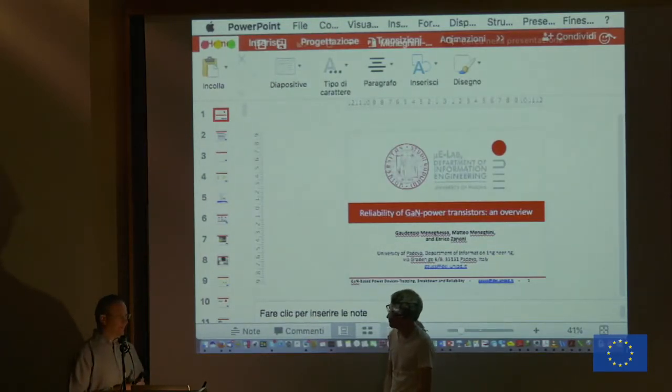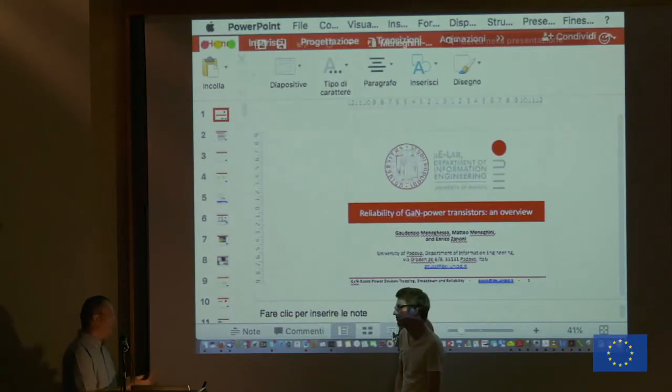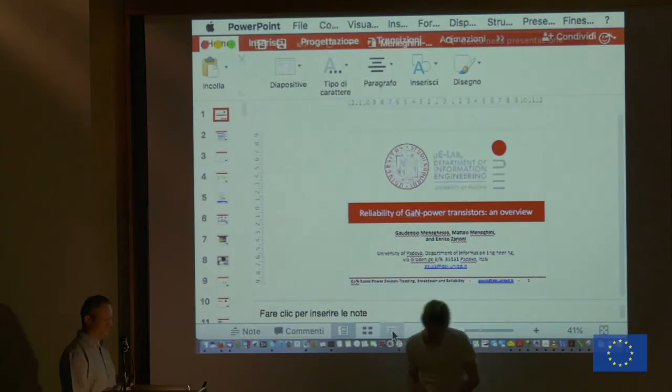So for the P-GaN gate, to increase the reliability we have to work on the material for sure, because we need a more stable material with fewer defects. But indeed we need to design our gate in an architecture that lowers as much as possible any accelerating mechanisms for the degradation. So you are right.